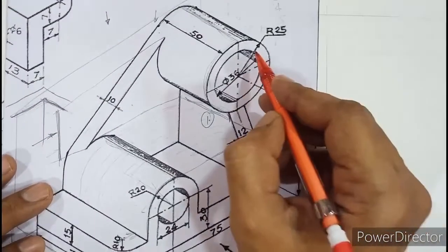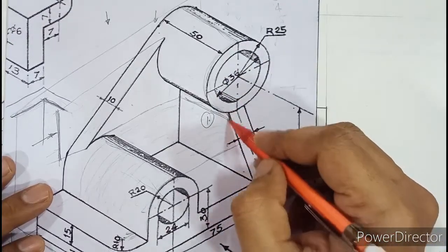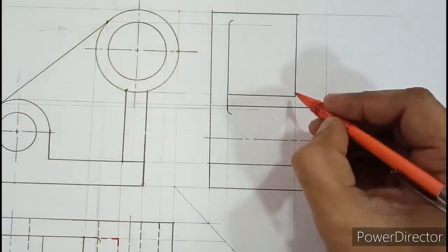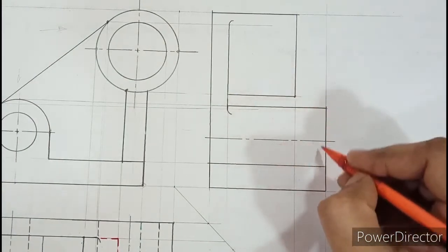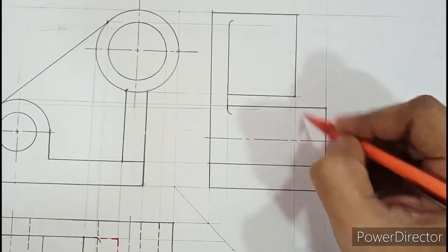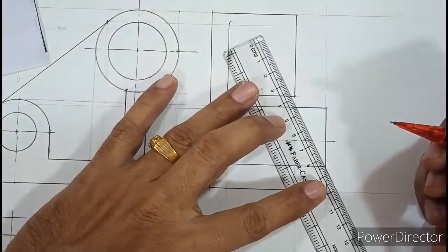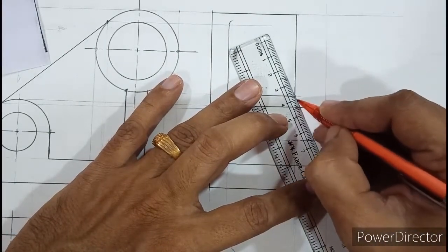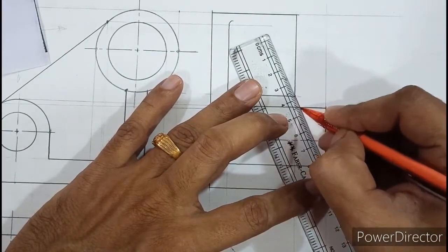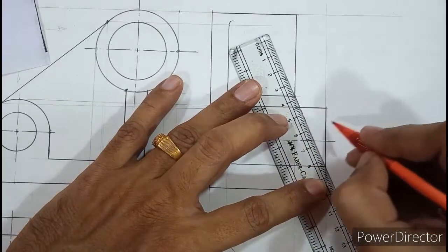So if you try to connect the top cylinder with the base, that is the inclined edge, what do you think? The number 1 rib will start from here and go down till here, but some portion you can see and the remaining cannot. So how will you achieve that? Align your scale and see, some portion you have to draw dark as I have done, and for the remaining you need to leave a small space and draw a hidden line like this.